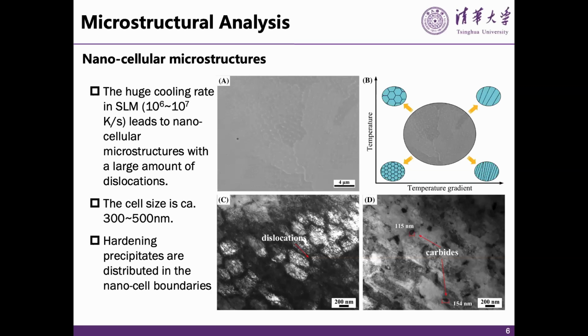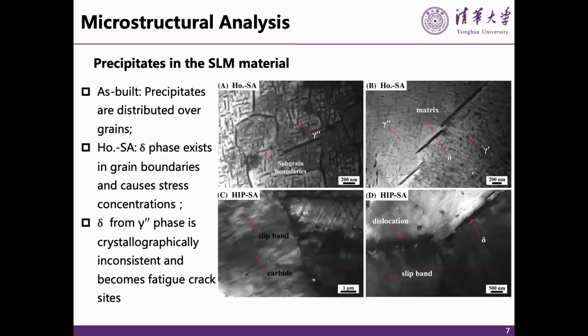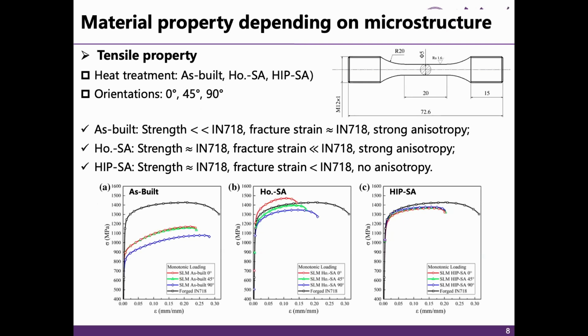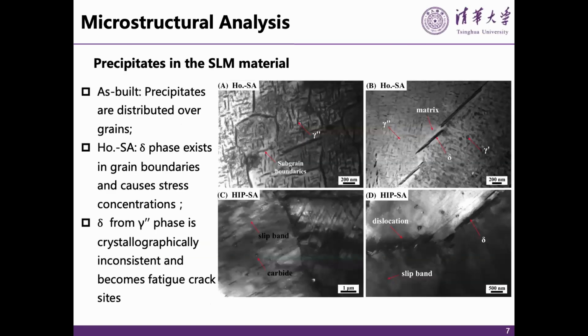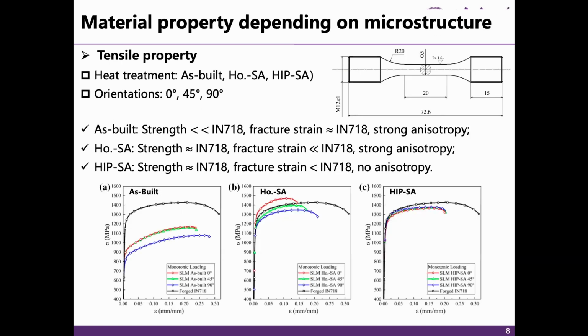This is very typical in a superalloy. We see this kind of structure not only in this printed material, we can also see it in cast material. Therefore, grain size affects material properties, but it's not the dominant factor. At the macro scale, these features are not affected by grain size. Therefore, even after HIP, when the grain size changes suddenly and much more severely, the stress strain curve looks very similar. That is a picture showing that in different states we have similar curves.